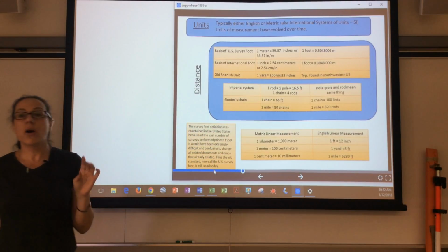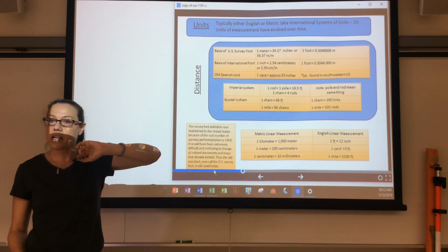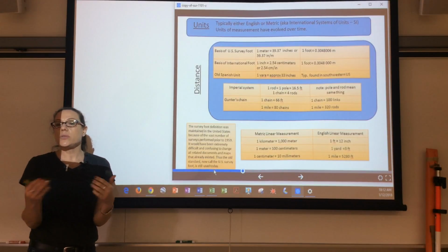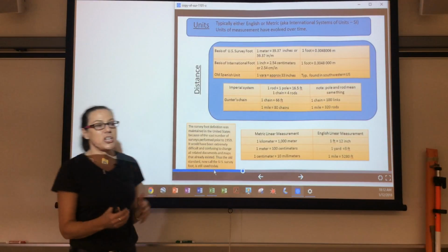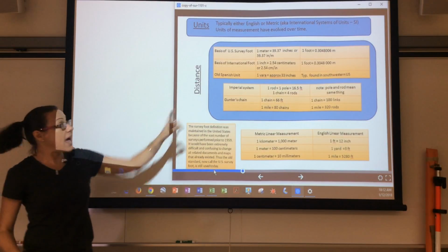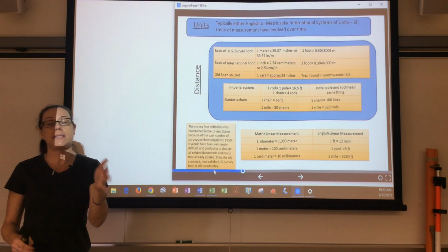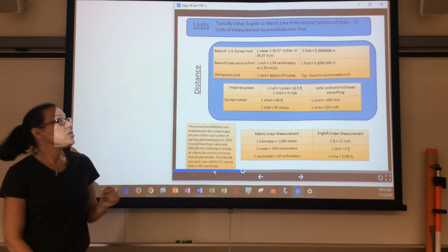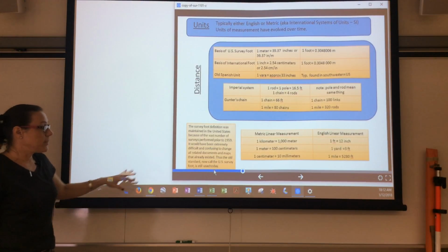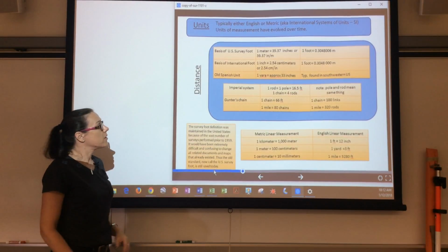Now you don't think that 0.006 at the end, way down there, is going to matter that big of a difference. It doesn't at a short distance, but when you start multiplying by 1,000, 10,000, 20,000 miles, that becomes a major error. That becomes a bust in the data where you thought something was is now not there. Okay? So almost always we use the U.S. survey foot. Just remember that if you do get to work with the surveyors.